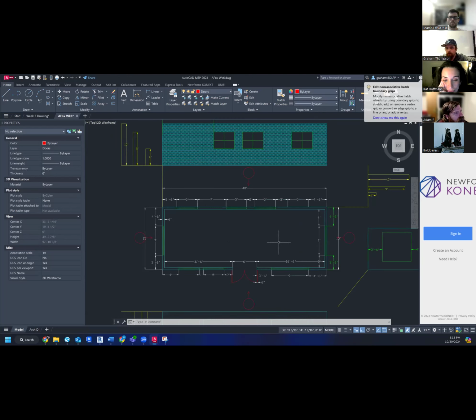When you place a receptacle, when you place a light switch, in any modern program, that symbol not only has a symbol, but actually has a 3D light switch that goes with it. Well, that light switch they're placing at 6 inches off the ground because they're not paying attention to where it goes. So anything in an architectural model as far as plan placement goes is probably pretty good. Elevation wise, it's garbage, because they're used to looking down at symbols and making elevations with 2D stuff. And it's all just based on line work, same way you're drawing it right now.